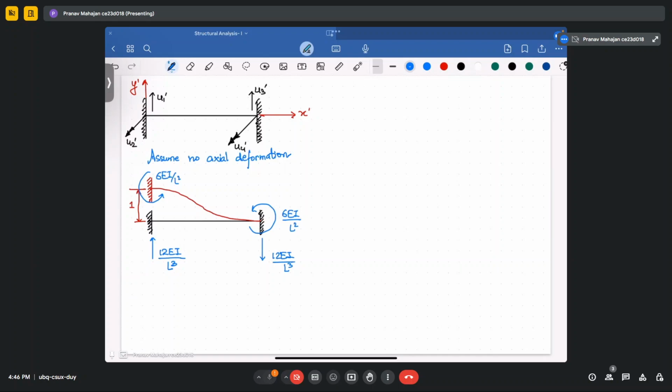Okay. So how do we define the stiffness also? In this case, since you are providing the vertical displacement, the vertical direction reaction would be K11, and due to the application of vertical displacement, the rotation in joint 1 will be written as K12. Then third, for joint 2, it will be written as K13, and this will be written as K14. Okay.